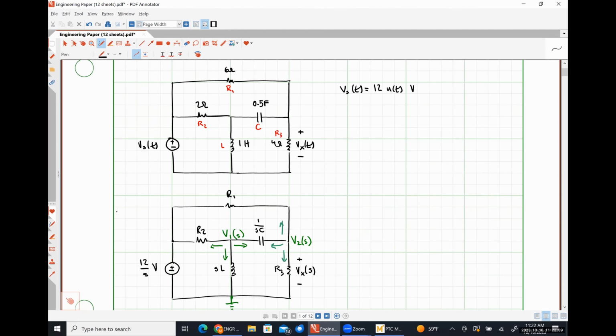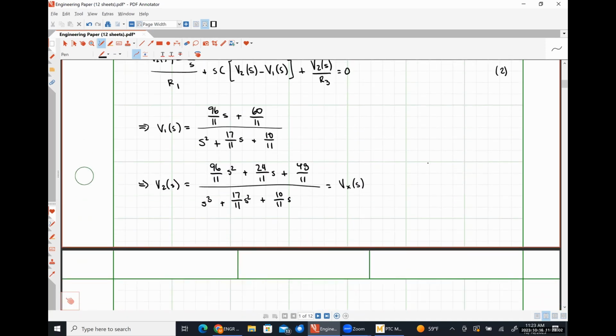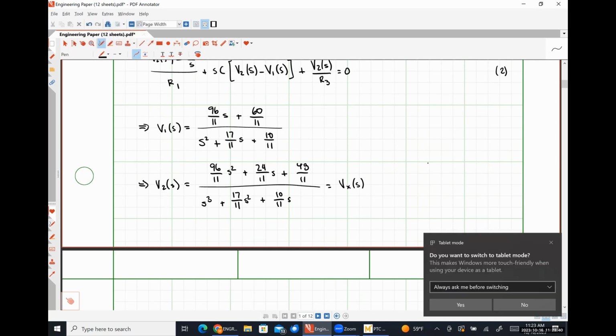So we've used MathCAD to get to this point. Our goal is to figure out what this voltage is in the time domain. So what do we do now? Partial fraction expansion and then the inverse Laplace of that. So this is a simple third order polynomial. We can very obviously see that one of our solutions to this is going to be s equal to 0 because there's a common factor of s. Let the monitor catch back up.